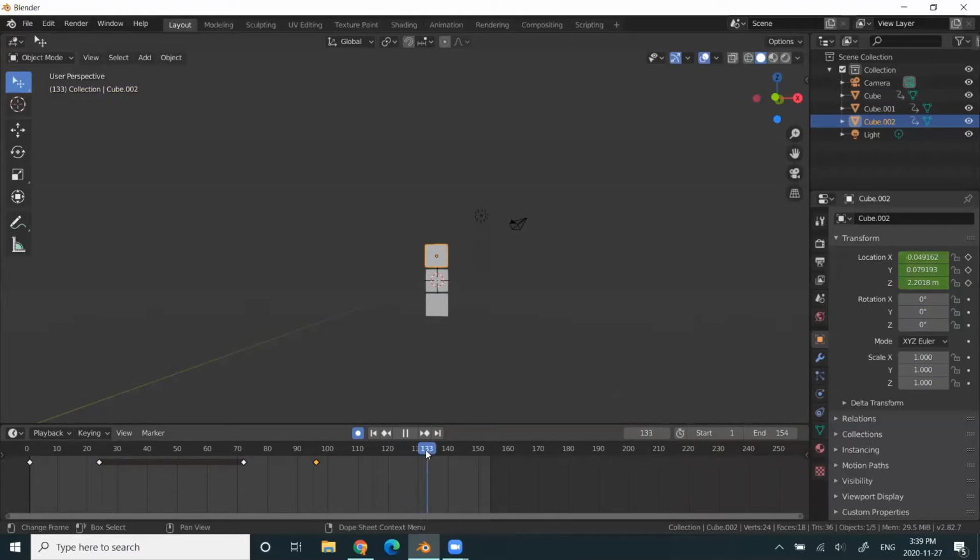Well, it doesn't have to be exact. I can set a keyframe there and a keyframe here. So now there's 2 holds here. So when we play the animation, it should come apart, hold, and then come back together, hold, and it's going to start looping just like that. So this is what an exploded view should look like, as it pulls apart, holds, and then comes together, holds.